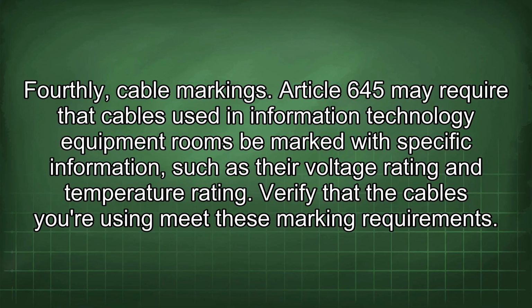Fourthly, cable markings. Article 645 may require that cables used in information technology equipment rooms be marked with specific information such as their voltage rating and temperature rating. Verify that the cables you're using meet these marking requirements.